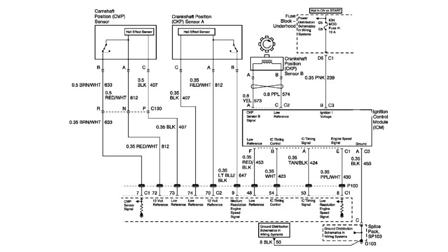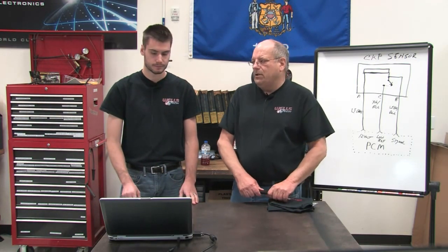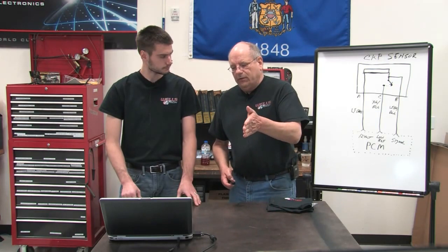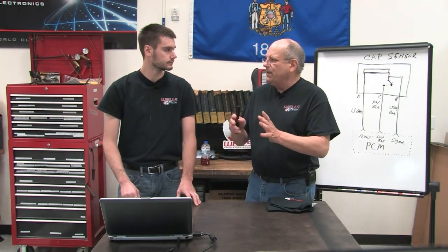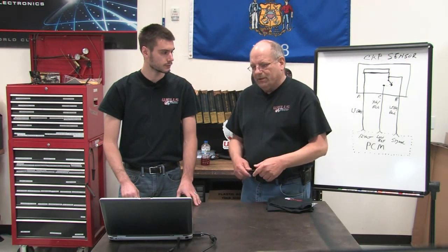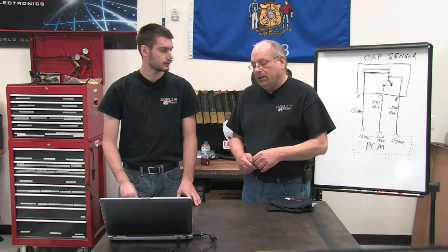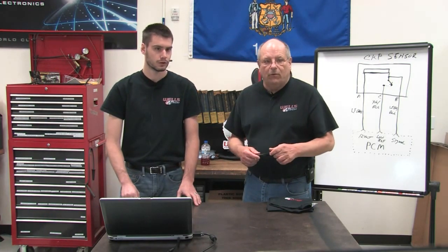It's got 24 evenly spaced windows or triggers, and there's no sync or keyway or anything on there that has a set difference like our 7 times does, where you have the 2 that are 10 degrees apart. The ICM knows that's my signal to number 1 cylinder top dead center. But there's no indication or any sync on that front crank sensor, the 24 times.